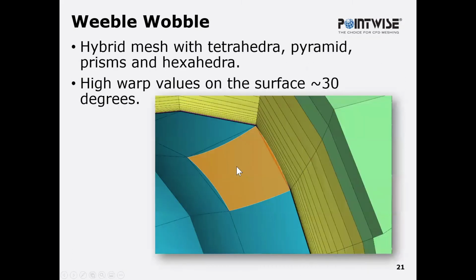And when you then instead have a quad dominant surface mesh, which is a hybrid mesh with tetrahedra, pyramids, prisms, and hexahedra, you find again you've got both convex and concave edges to a single surface element, as shown here. So yeah, it's a tricky test case, but the methodology has worked very well. So it's on this hybrid mesh, mixed cell types, and mixed order.